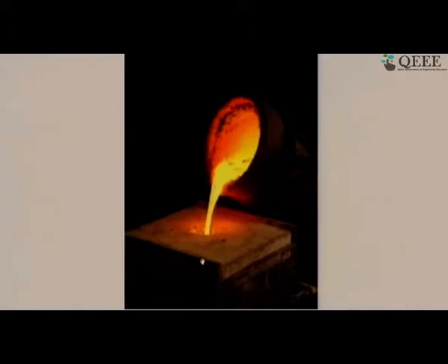So that's how we have to ensure that it doesn't solidify before the mold is completely full, and at the same time we have to make sure that the mold gets full completely with metal and there are no air pockets or bubbles in it. If those are there, then the component gets rejected. So there's fluid flow here, there is convection heat transfer taking place. The material here is not air or water, but a liquid metal.